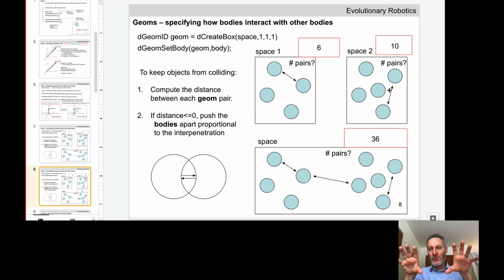Most of the time in that swarm, we're assuming the robots are not all on top of one another. They're physically separated, so we can speed things up. If we don't use a contact space when simulating a swarm of robots, then the physics engine needs to determine potential collisions between any object in any robot and any object in any other robot.